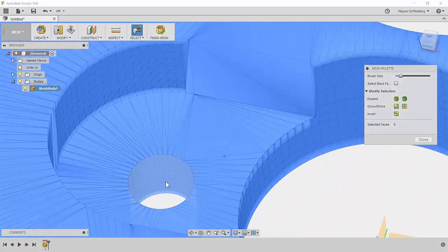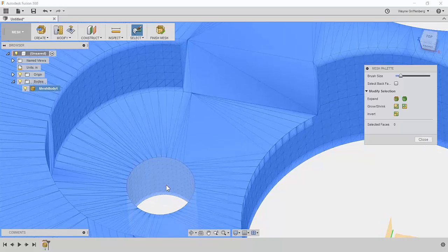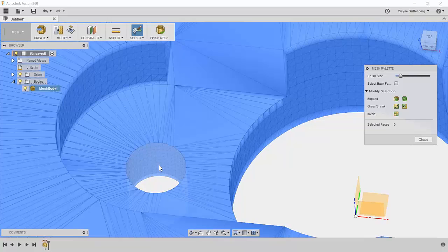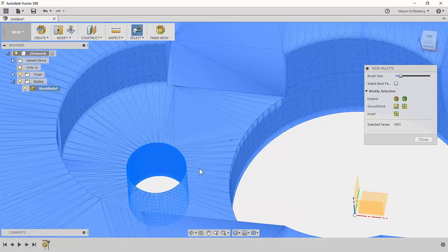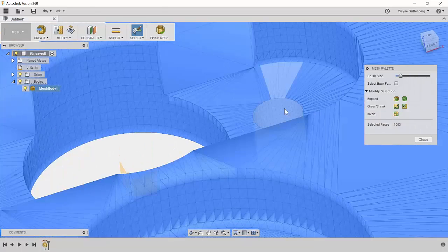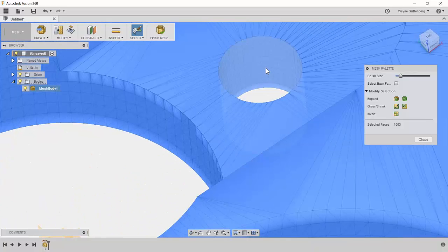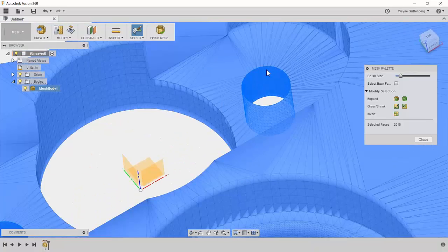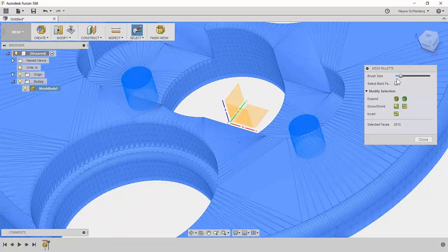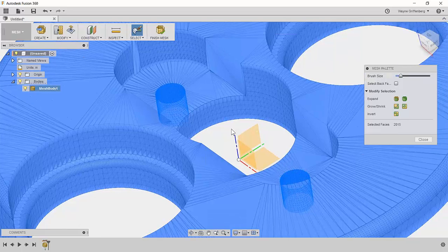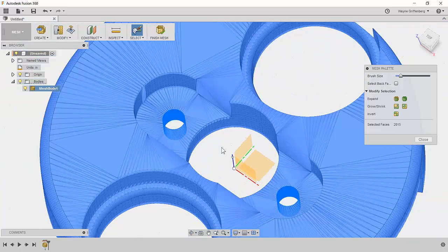While I'm in this hole feature down here, it's not really a hole. It's more like what would be a hole before it was made into an STL. As I drag my cursor through, I can select those facets, and I can also select another hole here as well. I'm just going to drag through until it looks like my paintbrush is all the way in that hole, and I can select that hole too. So it just gives me the ability to change the number of facets that I'm grabbing. I want to grab those two holes and delete them.